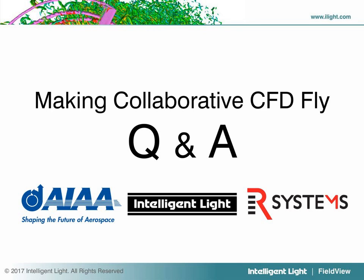This is Michael. I have something to add to the previous question about XDB over remote graphics. When you're using the XDB, you get a lot better latency and performance when you're viewing and modifying your model. To do high-performance remote visualization, you generally need to submit to a 3D accelerated viz queue, which increases costs and still increases the latency from your interactive session. So efficiency and responsiveness from the interactive point of view, and it also costs less because you don't have to reserve a 3D capable node to then launch another third-party solution to do remote 3D visualization. Right, and one of the things within FieldView is that we do client-server, and that's another way we can do our graphics.